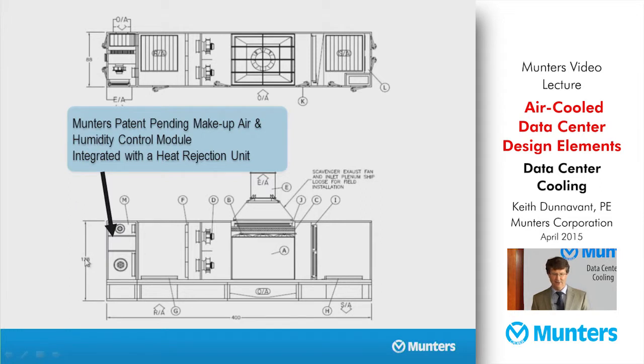So that's your makeup air system, and Munters has some innovative makeup air designs, both standalone and designs that will integrate with cooling units. So here you see a sample cooling unit that has hot return coming back with optional filters and supply fans and some other components that we'll talk about in another segment. But the makeup air module can append right onto the end here, and it has everything you need to have proper filtration of the makeup air, proper humidification, and proper dehumidification.